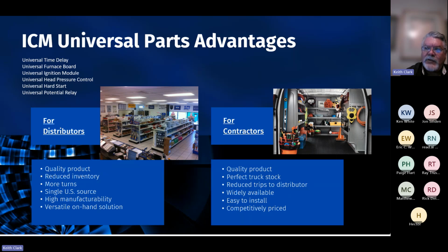Ignition control module, the ICM2918, replaces almost 300 different spark ignition modules. And then the universal head pressure control replaces all single phase head pressure controls. Our legacy models are all replaced by this universal head pressure control, and just about everything in the field that has ever existed in the head pressure control market. ICM is definitely the leader in that particular product, and this will work with 2 temperature or 2 pressure probes, and it's a universal voltage, very easy to set up utilizing NFC programming technology.